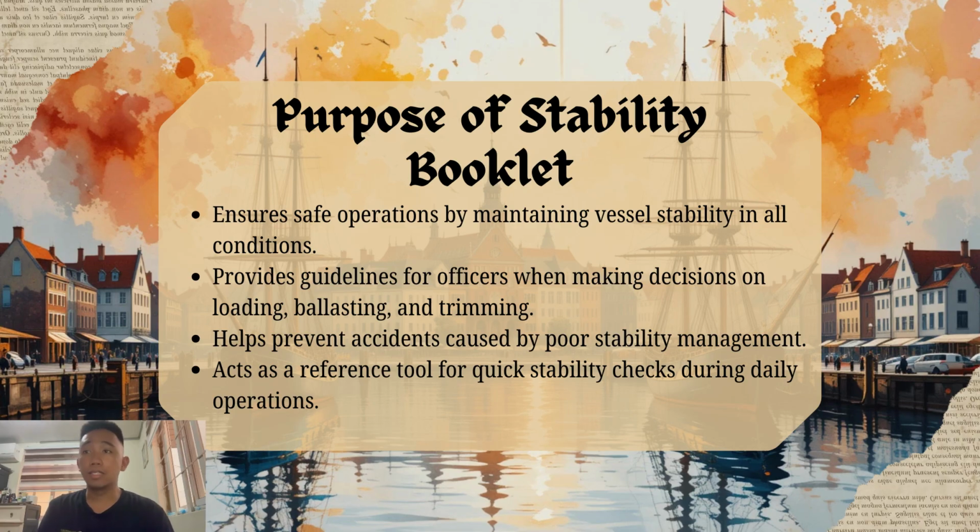Stability booklets are critical documents on board a vessel that provide information and guidance to ensure the ship remains stable and seaworthy under all operating conditions. It supports the safe loading, unloading, and operation of the vessel, ensuring compliance with maritime regulations and helping prevent capsizing or losing control. This includes key data like hydrostatic stability curves, loading conditions, and damage stability, and is primarily used by ship's officers, inspectors, and surveyors to assess and manage the ship's stability.